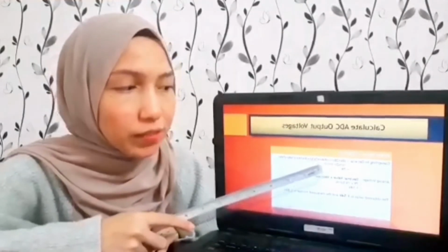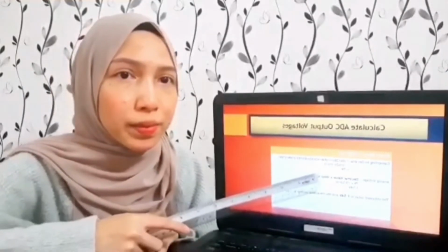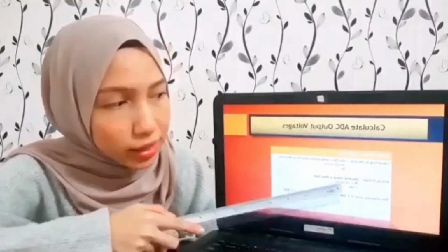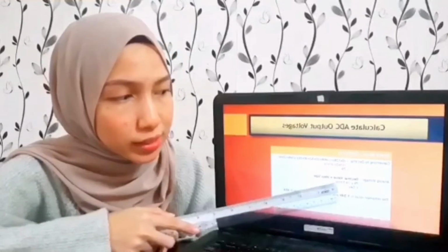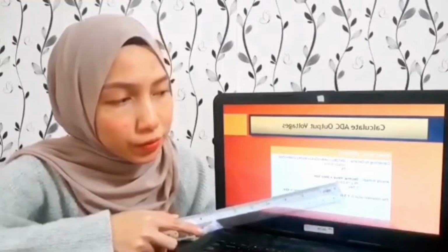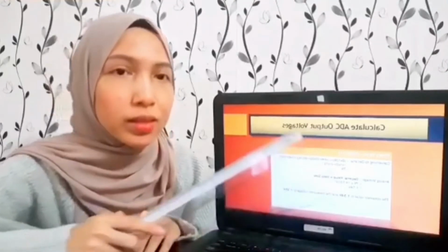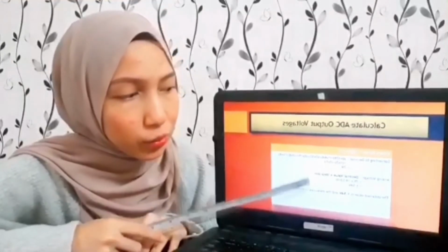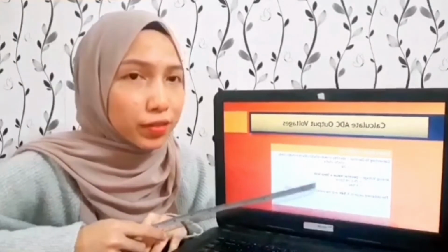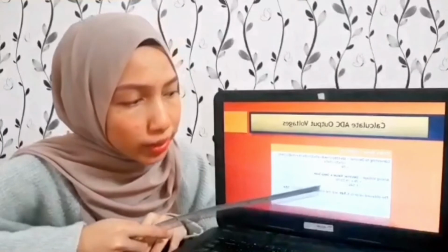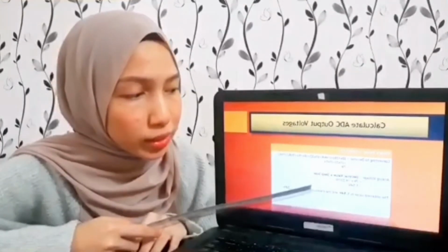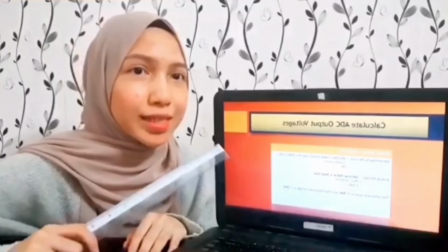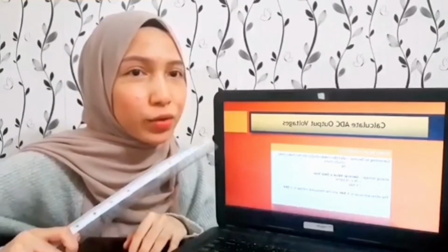We get 79 decimal multiplied by 19.53 millivolt, and the answer for the analog voltage is 1.54 volts. Lastly, the obtained value from the calculation is 1.54 volts, while in the simulation, the measured voltage is 1.55 volts. That's all from me, and I will pass to Adila.